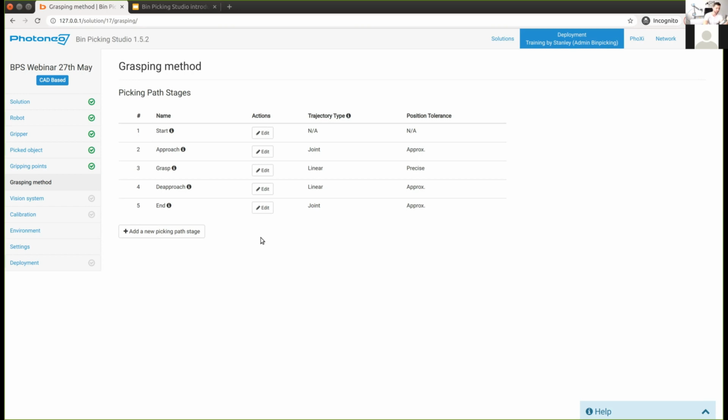And in the middle, we have a couple of more waypoints. We generate waypoints in the space to actually help path planning. And why we need to do it is because the path planning can be a slow process. It will explore millions and millions of combinations of the joints because it is basically a 6-dimensional space.